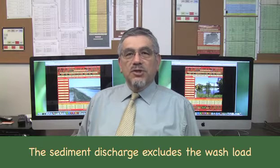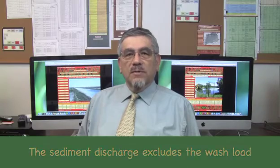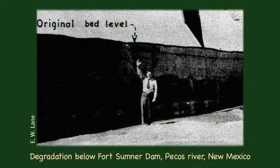The sediment discharge is the bed material load. It excludes the fine material load, or wash load, which is transported through the system largely without affecting the river hydraulics. This photo shows the effect of releasing sediment-free water from a dam. A reduction in sediment load caused a reduction in bottom slope downstream of the dam, triggering channel degradation exceeding 3 meters.